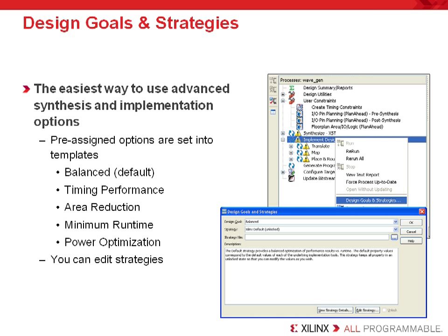Now, we also wanted to show you an easy way to set your XST synthesis as well as place and route software options. Xilinx provides you with the preset software options that are part of the design goals and strategies. This is an easy way to run both synthesis and implementation without knowing how the software works. This is helpful if someone does not want to understand the various options and when they can improve their timing results.